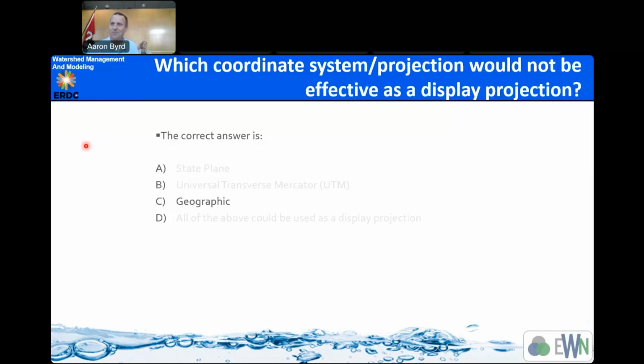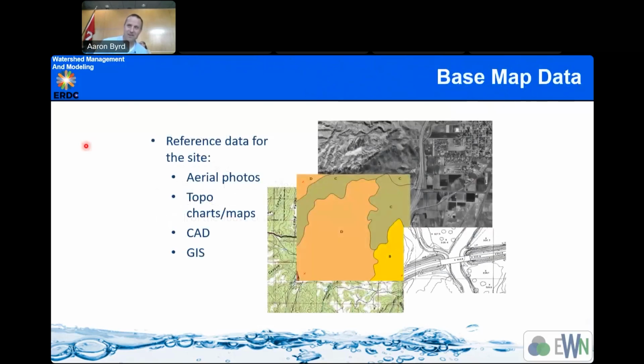So you've got to convert it. You'll have to convert any data you have. You have to make sure your grid is not in geographic. You have to make sure your grid is in some planimetric projection. You could probably make a grid in WMS in geographic, but it won't be right. Your model won't work. It might work, but it won't be right. Worst case scenario.